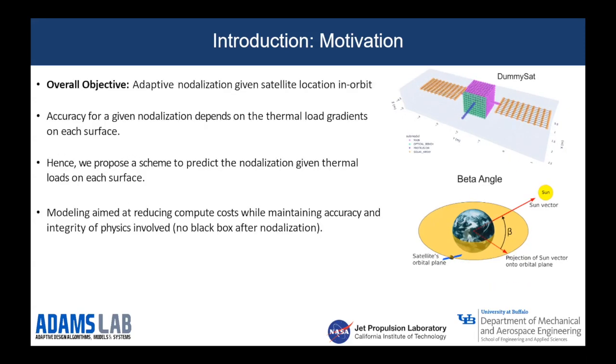Okay, so how do we propose to use PIML, this hybrid technique, to help us do onboard thermal simulation? One of the pain points is how to actually generate a nodalization to represent a spacecraft. As you can see, this really complicated model on the top right is called DemiSat, which we made up for this problem, of course. If you assign this problem to a junior thermal engineer and say, give me a really accurate model, they might tend to over-nodalize the entire spacecraft, right? Let me crank up the nodal density to as much as I can visualize, and then that should take care of all gradients and so forth.